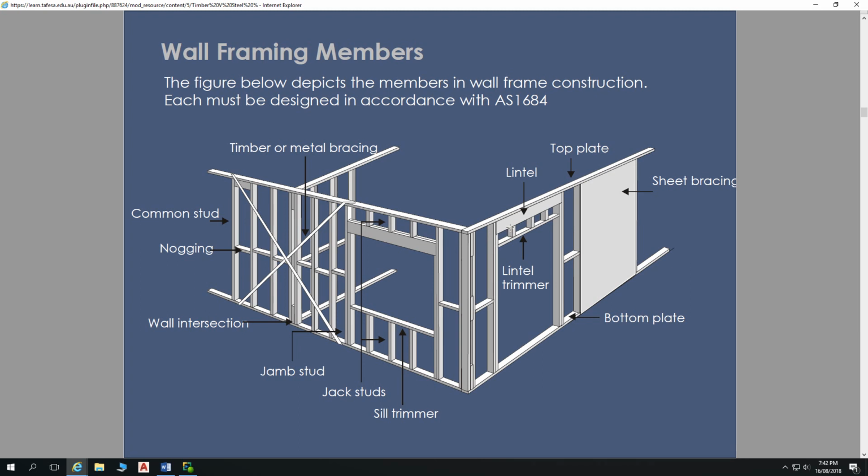So sometimes you've got lintels that are 63 wide in a 70 by 35 or 70 by 45 stud. You cut 63 millimeters out of 75 millimeters, and you're just left with 12 millimeters of timber. There's really no strength in that, and it might as well be trimmed straight off, because it doesn't give much to fix that lintel to for overturning anyhow.